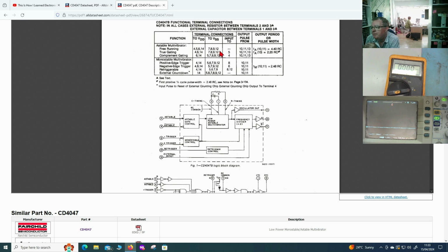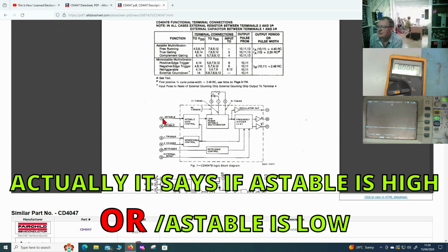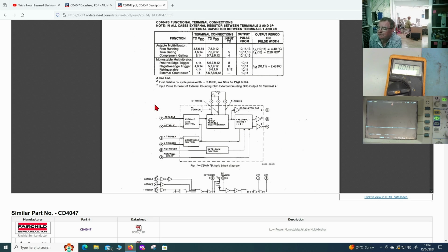where they should be. Now, the suggestion made by Max was that we have this input 5 as high, and this one, which is the low input or inverted input, is also high. But the rule says that if one is high or the other, then it will work. And we can see from the example here that 4 and 5 are both connected to supply. So that isn't what's causing the problem. That is normal. And somebody else comments further down that that is normal.